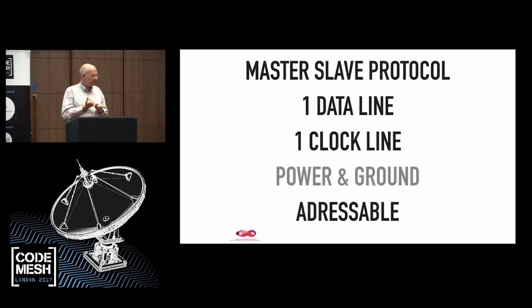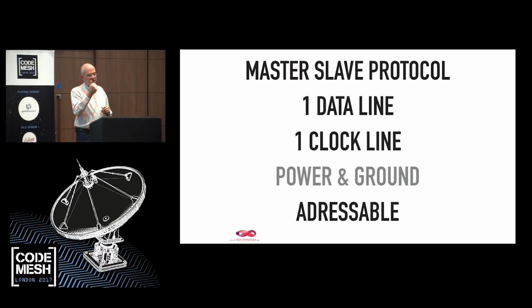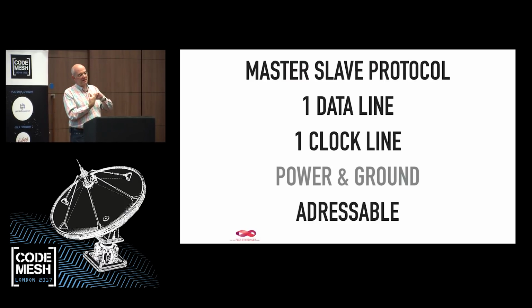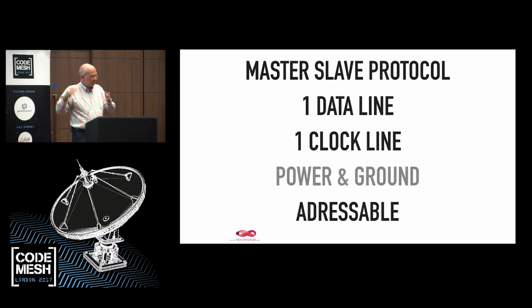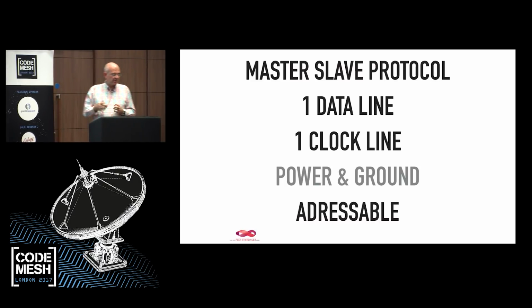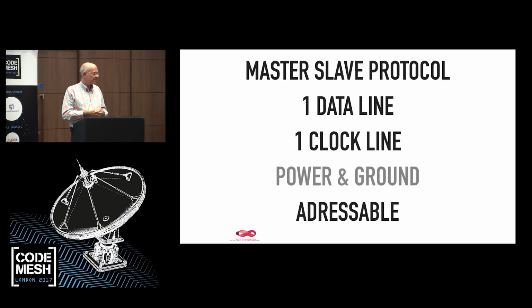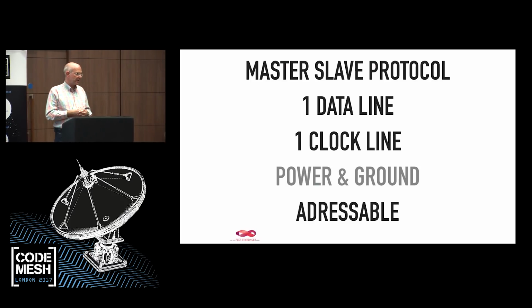It's addressable, so we don't need the chip select line. And because it's addressable and it's a little bit more complicated protocol, you actually need only one data line because you basically send a read, address, and then the chip basically sends the answer back after you're finished. However, the advantage is addressable, so you can have much more I/Os on one board. The disadvantage is it's slower. It's limited to 400 kilobit per second.